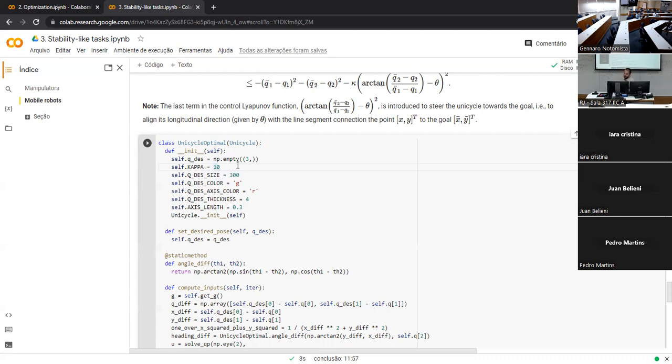And the Lyapunov functions are functions that are used to, in a way, check the stability of a system, which means the stability of equilibrium points in general, which means if x is going to go to x bar, you can check it using a Lyapunov function. A control Lyapunov function is a function that is useful to pick a control input for that to happen, and that's what we did. Right? So that is the etymology of the word.